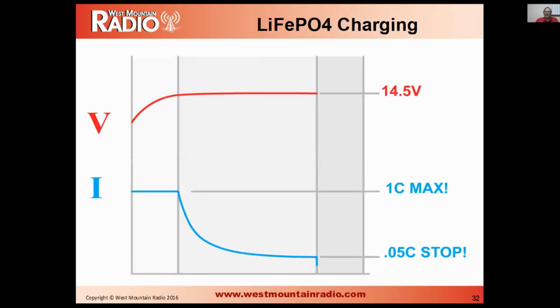The lithium ion battery has the same first two stages. However, once you get to a certain point where the battery stops, or at least is only drawing a little bit of current, you need to stop the charging altogether. The lithium ion battery is the opposite of the lead acid battery in that respect. It doesn't want any additional energy in it. If you do put additional energy into it, it'll overheat.